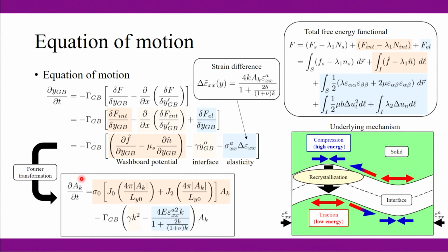Okay. So still, the key ingredient we just introduced before is about elasticity, but now that is considered the surface energy. So the surface energy contains, like here, the interfacial part, right? Those two things. So basically, it is those two contributions. That's right. And if you do the functional derivative, in the end, you are going to pick up the coincidence site lattice contribution. So you will have something related to the washboard potential.